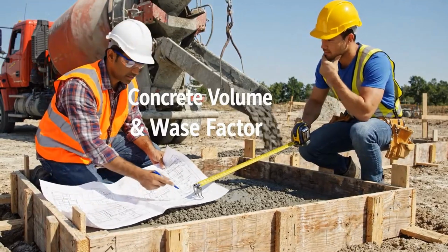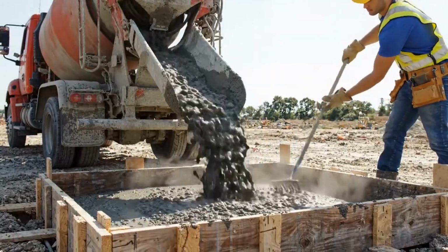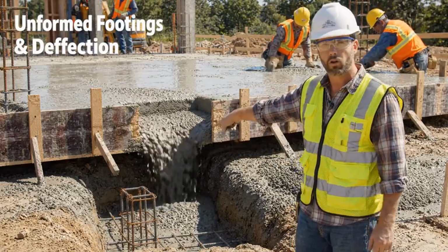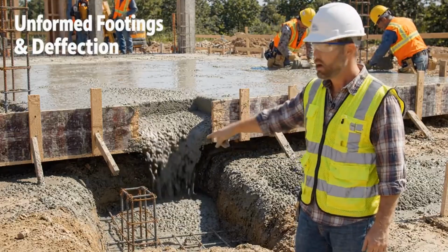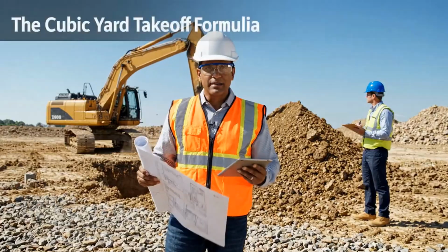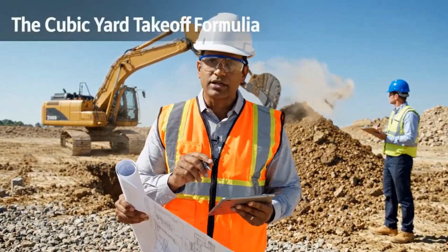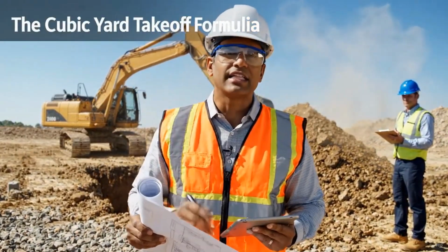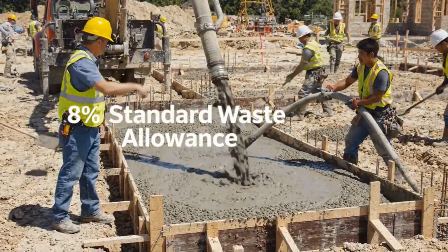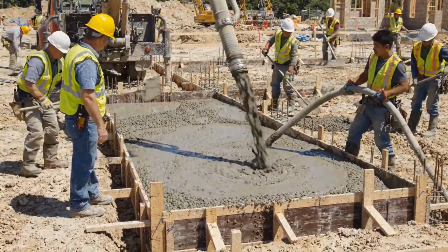Calculating concrete volume seems simple on paper, but ready-mix orders are rarely just length times width times depth. When you are calculating orders for unformed earth-cast footings or elevated deck slabs, over-excavation and formwork deflection will eat up your material fast. To compensate, estimators must use an adjusted volume calculation formula that incorporates real-world site conditions rather than neat line drawing dimensions. An 8% standard waste allowance is your baseline protection against subgrade unevenness, spillage, and pump line holdup.